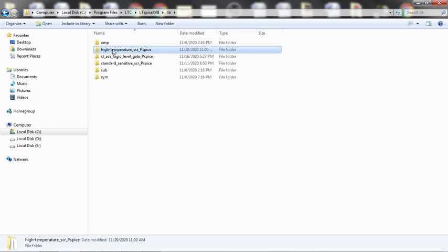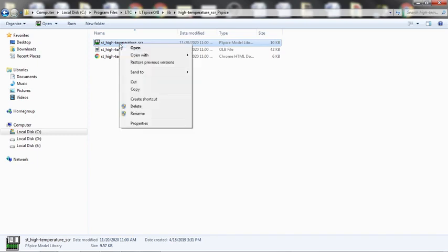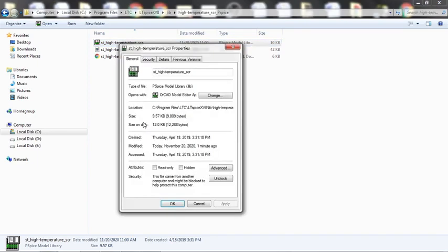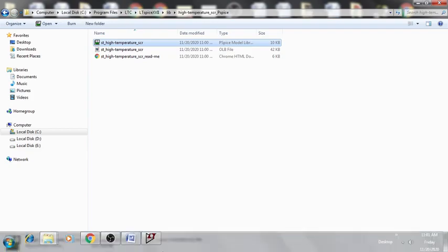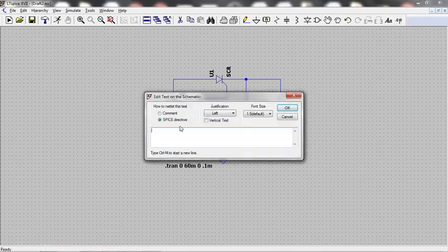Okay. So I require the path of this. This is a lib file, library file. So you take the path of this, go to properties. So you add that path here. So right click here, write .inc include. Click that path. Copy the path. So it is in this path.